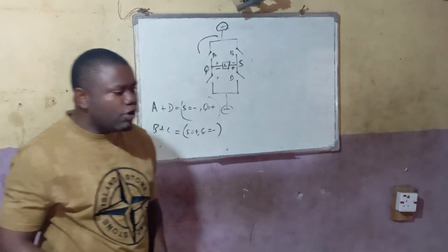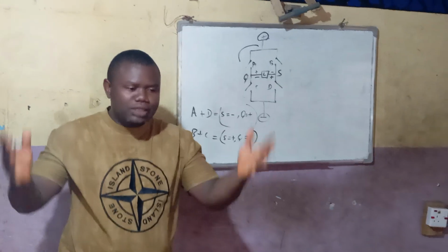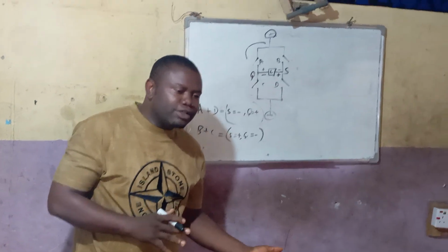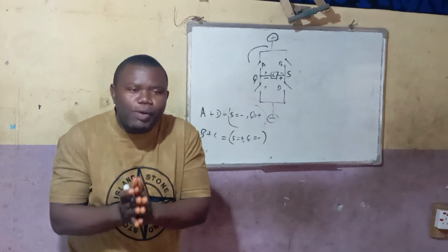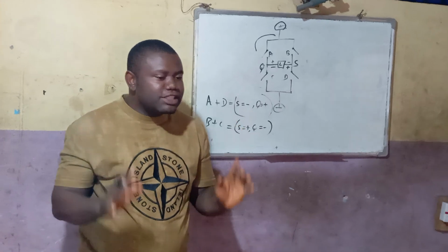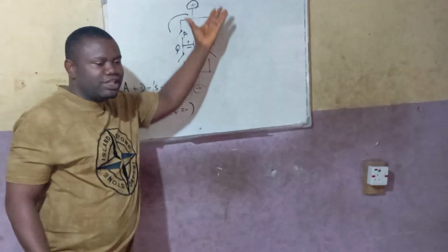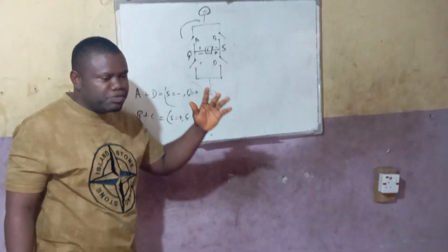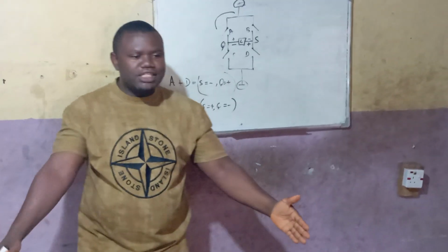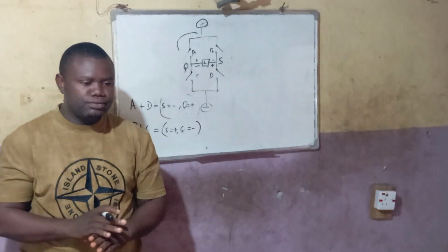True. That is it. Now, what is DC power? DC power is that type of power that just flows in one direction. It doesn't have change of polarity and stuff like that. But AC power is a type of power that actually changes polarity with time. And this is what we want to achieve, changing of that polarity. And that's why we are here with this H-bridge technology. With H-bridge technology, the terminal that was positive now becomes negative later. The terminal that is negative later is positive now, and it keeps changing.